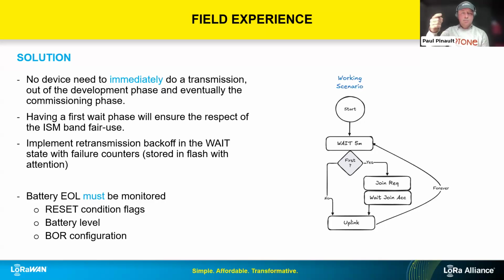So it is rejected. And the device has great difficulty joining because you have to retry the join until you get a nonce that is higher than the highest one that has been randomly chosen previously. This is polluting once again, because you have join requests cycling until they find a good number, and it causes trouble joining the network. So that's just a simple setting you have to take care of. Yeah, a great example. Thank you.